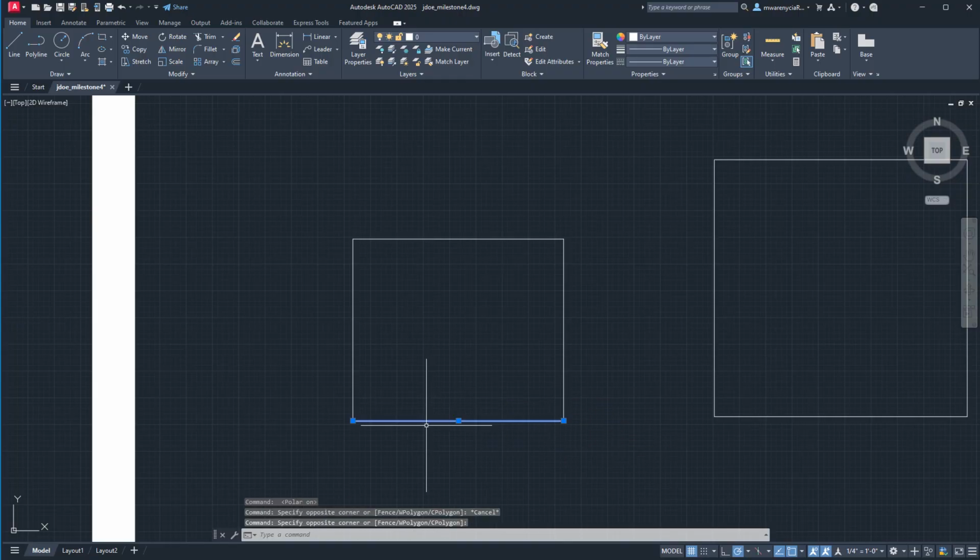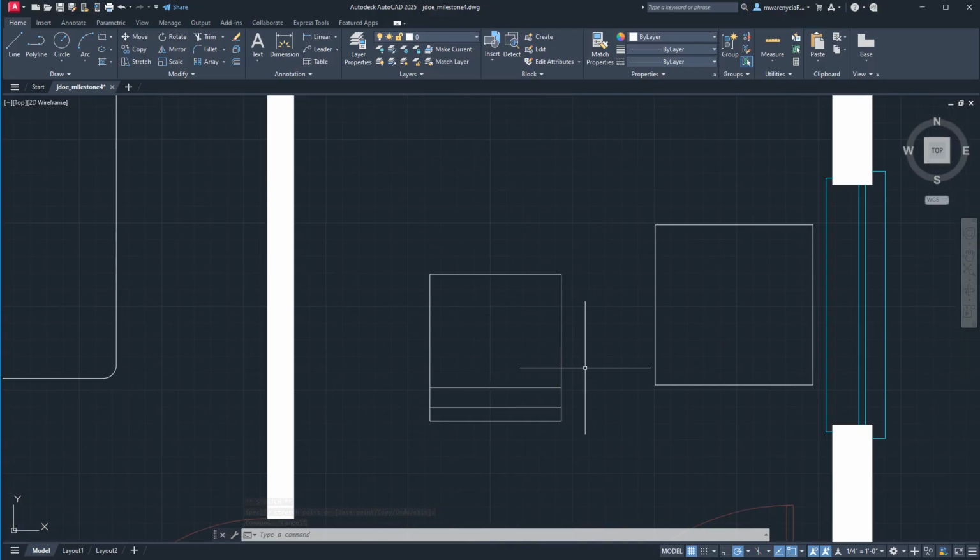And then again, we'll offset this another 5 inches, and that'll represent the back of this seat and how far up it goes. And then I'm going to offset it another 2 inches because this is sort of a flat plane you'd see. And then from here we can call it at that, or we could come back in and just do something like move this in, say 1 or 2 inches, if we wanted to kind of spice this seat up.